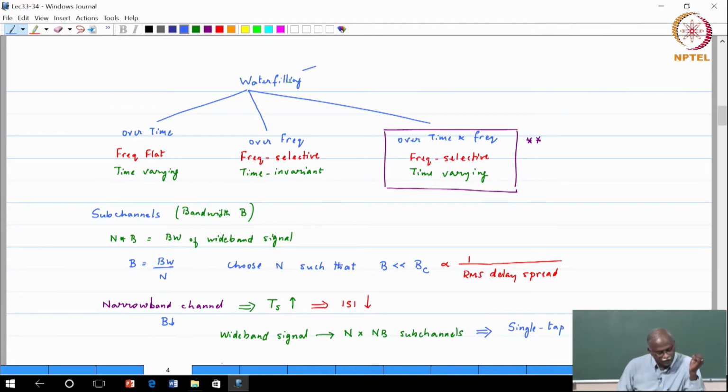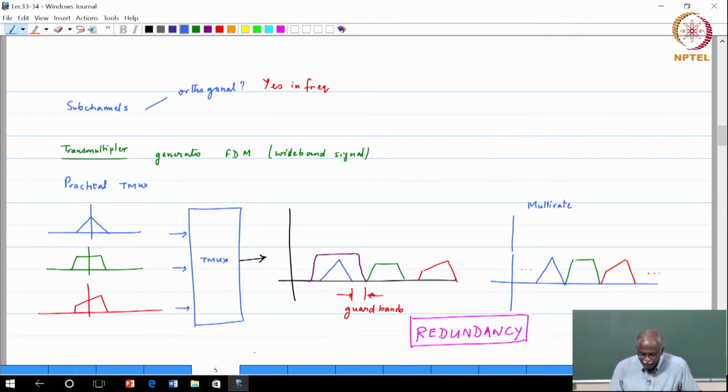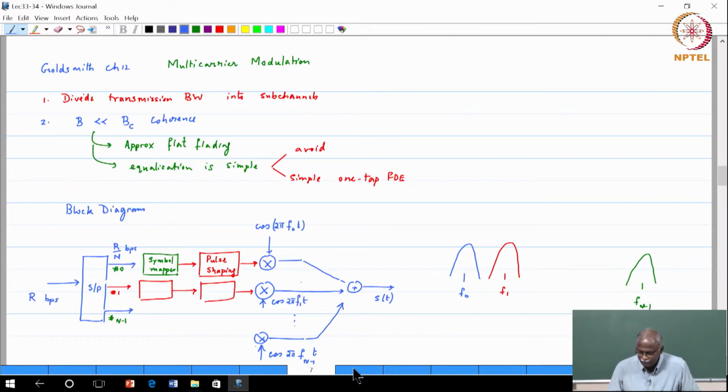Okay, so that is the summary statement. So the move now is towards the understanding of the multi-carrier systems, where we say that okay, wideband transmission, I want to do it. So we referred very briefly to the history of multi-carrier modulation. Multi-carrier modulation basically took multiple streams. It could be from a single source, right? Very often it could be from a single source. All you are doing is parallelizing them. It could also be data for n users. Each of these streams corresponds to a different user.